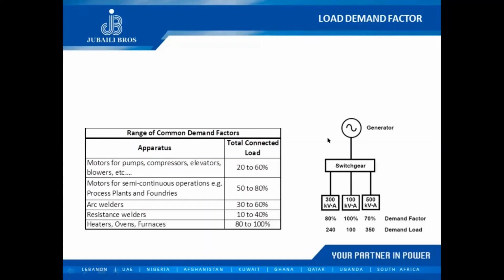Now, typically speaking, and out of my experience here in Dubai, DEWA enforces relying on the total connected load when it comes to emergency power supply systems. There might be other regulations in different countries, but to be honest with you guys, I'm not aware of them. But I know for a fact that DEWA requires all diesel generators or all emergency power systems to be sized as per total connected load.